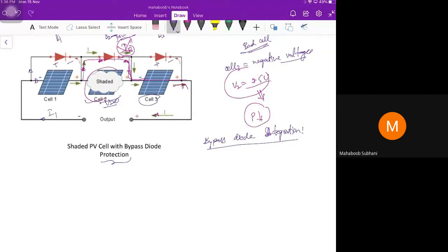Typically, a bypass diode can be provided across groups or substrings of PV cells, typically 16 to 24 cells, at the back of panels or within the junction box of a solar module. So for example, two bypass diodes are sufficient for a solar panel with a rated power of 50 watts.